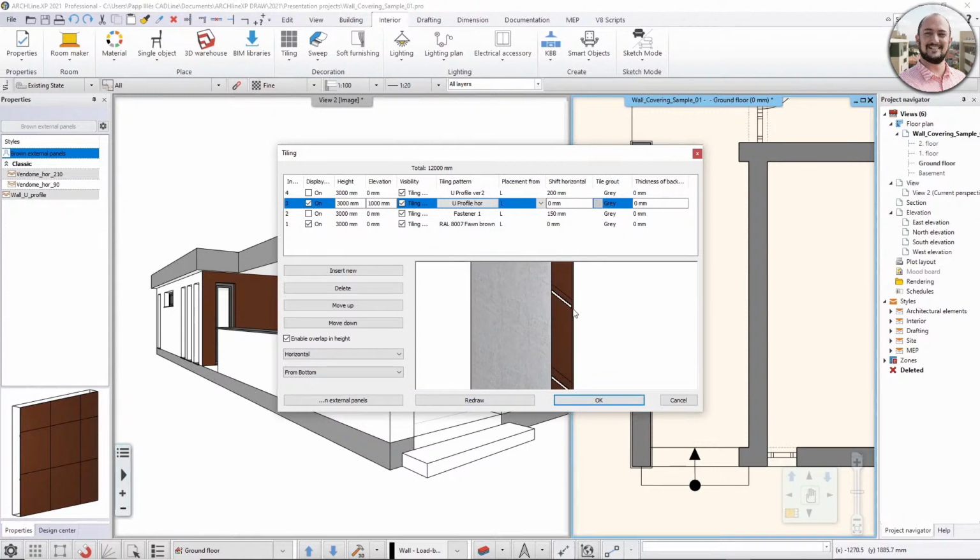What makes this bar appear here exactly? That is actually something that you can find as the elevation. Now if the elevation is set to, let me just change it to 900 and click on redraw. See, it's going downwards. Let me just change it again so you can easily tell how that changes. See, it's going downwards, and so now it's measured from the bottom. So I have set up a value of 1000 because this is where it should be, and then the software will solve the rest of the math.